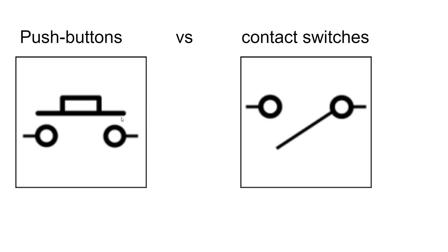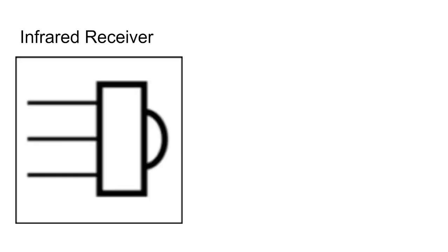Push buttons: basically, push connects the circuit. If it's not being pushed, same with switches, if it's not closed, it's not going to connect the circuit. An example of this is a keyboard, which is a series of buttons, and whatever one you push down connects a certain integrated circuit, and the integrated circuit can then tell the computer which buttons are being pressed. It can then send the ASCII number code, through binary math, to the computer to actually process.